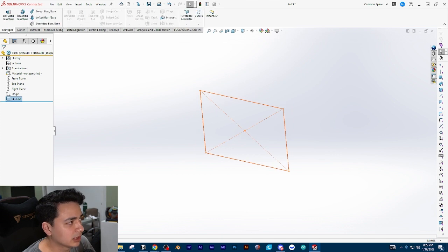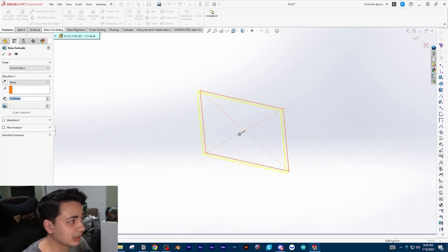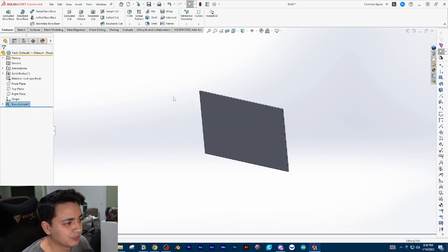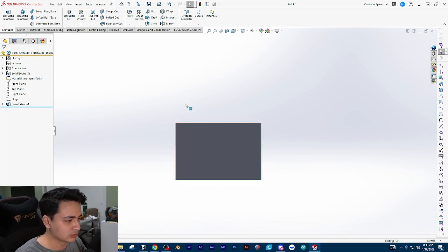And now we're going to add thickness to the sketch that we created in the 2D plane. So we're going to extrude this out. And we just measured the thickness, and we said our thickness is 2.8 millimeters. You just type that in. Boom. Okay. So this is just the front window of our entrance, right?